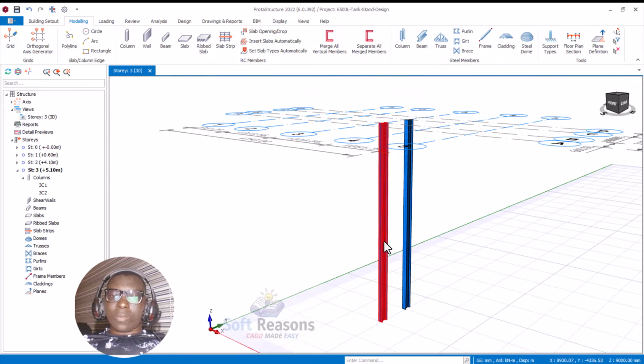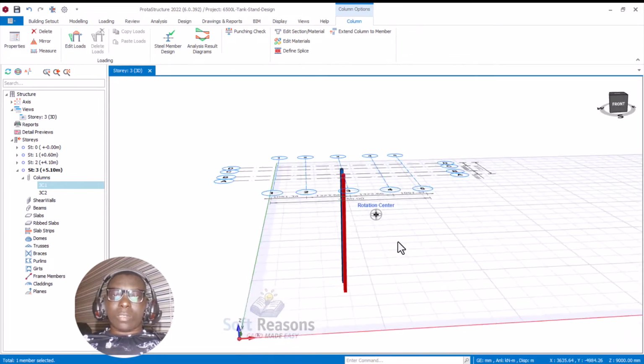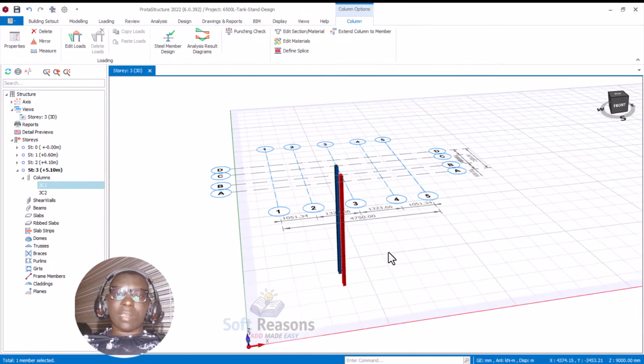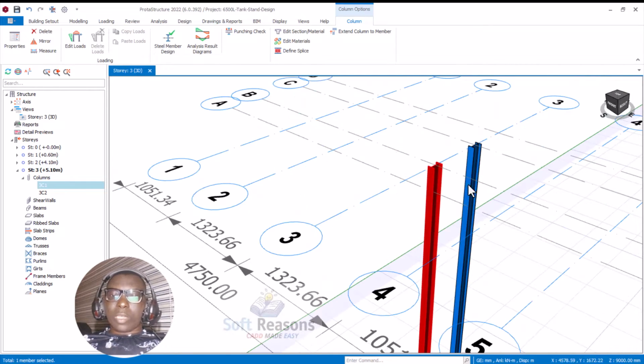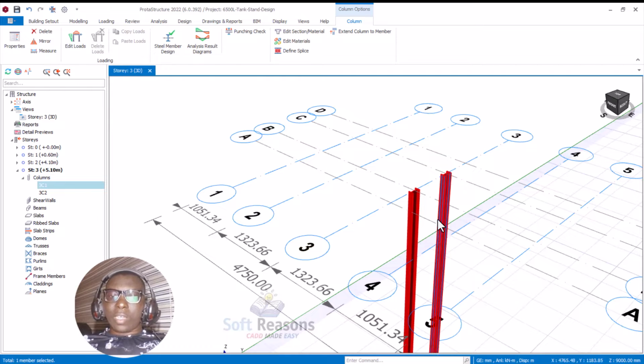stand, the height of the platform, is 4500. You can see it there. This is what I actually intended. So the next thing we are going to be modeling is the beam, the cross beam that will connect grid line intersection A3 and then D3 right there successfully.